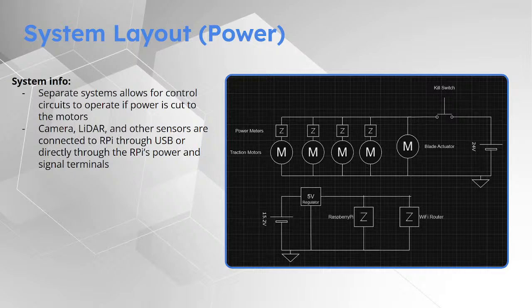Is your motor driver opto-isolated? No, it does not. That's one kind of downgrade we had from last year. That was all opto isolated. It had all that stuff built in, and this one does not. So something that we're looking into is either making our own boards for opto isolation or looking into different methods of ground isolation between the two systems.